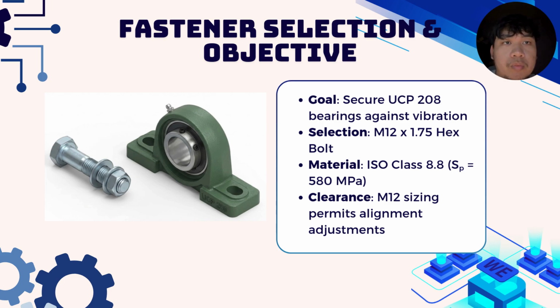Hello, my name is WILLDRON and I will be presenting the threaded fastener design. So our main objective here was to ensure the UCP 208 bearing housing are securely mounted to the conveyor frame and can withstand continuous operational vibration. To achieve this, we selected an M12 by 1.75 metric hex bolt.